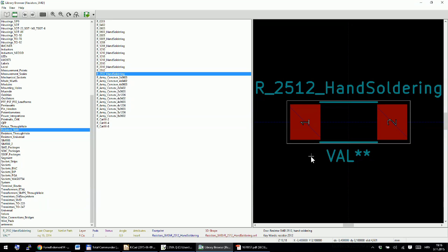Sometimes there are a lot of sizes of the same components. If you check, there are different sizes in the pads, so the exposed copper in your PCB can have different sizes depending on your use or the size of your board. Sometimes you just need your bare minimum copper if you don't have space on your board, so you can squeeze in as much as you can.